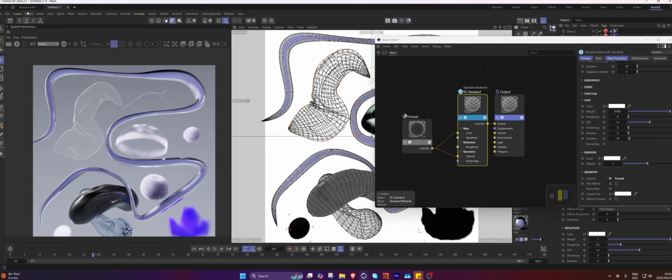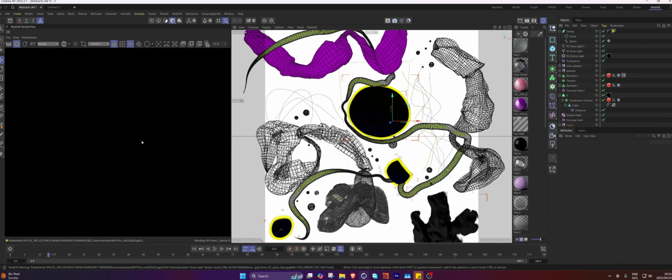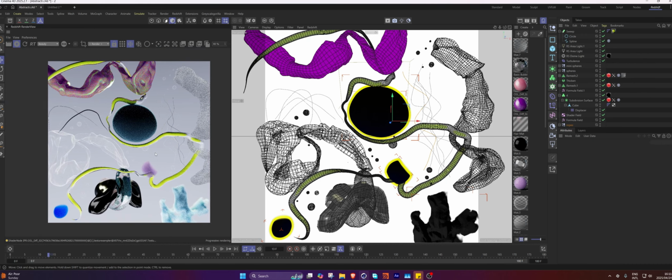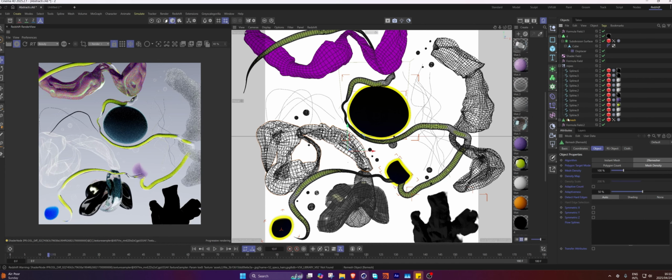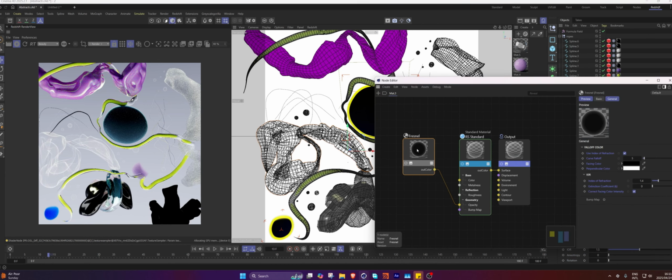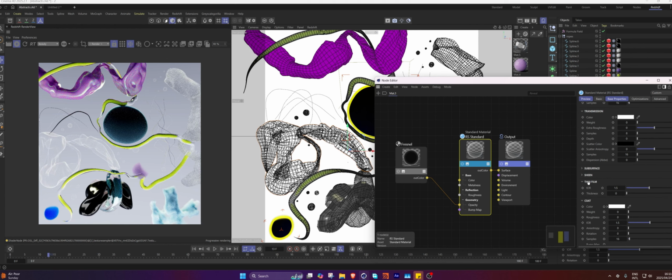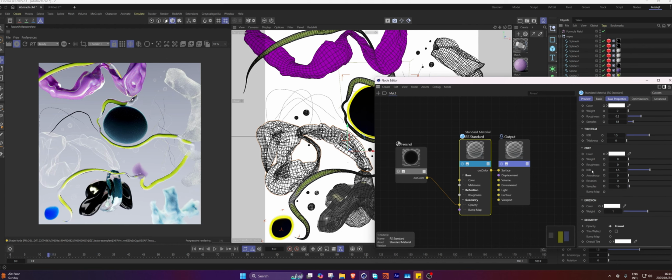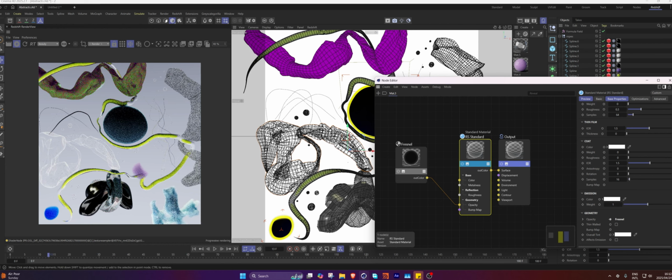I can go back into this project file and show you guys. Let's see. Which one is it? Yeah, okay, I literally just used the Fresnel over here. Just plugged into the opacity, but it's set to something like 1.4. Did I change anything else? IOR is the same. Okay, interesting. Oh, and there is also just a bit of emission. But yeah, it seems like it's mainly the Fresnel over here. But I think the reason that you can see it a bit more is that there's a bunch more movement in this specific spline over here.